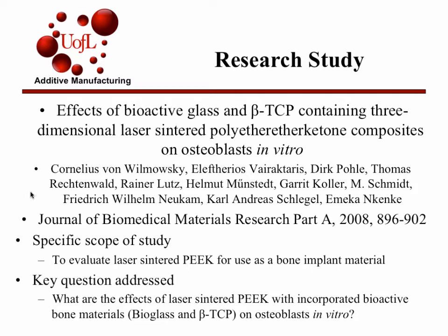The specific scope of this paper was to evaluate laser-sintered PEEK for use as a bone implant material. PEEK is already used as a bone implant material, however it's normally made by an injection molding process, and there's a need for a more direct manufacturing process to create complex geometry. So this is where laser sintering comes in.